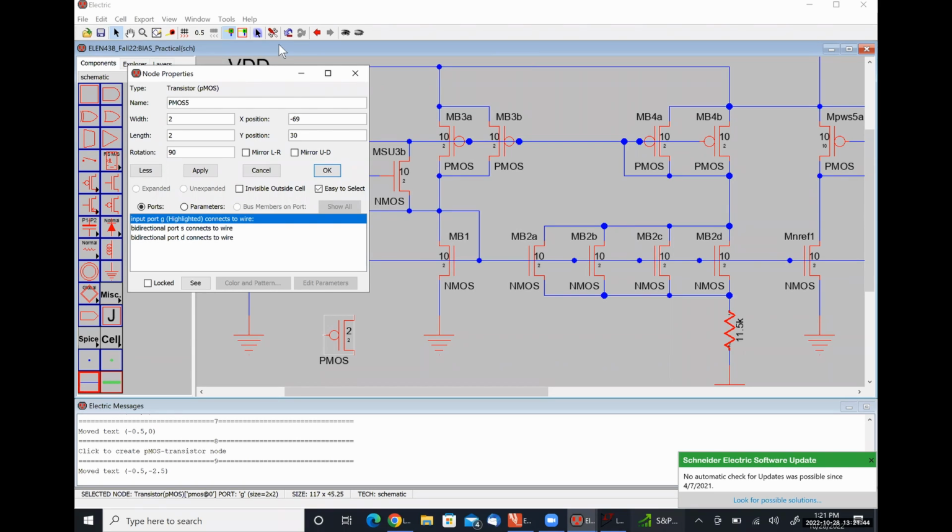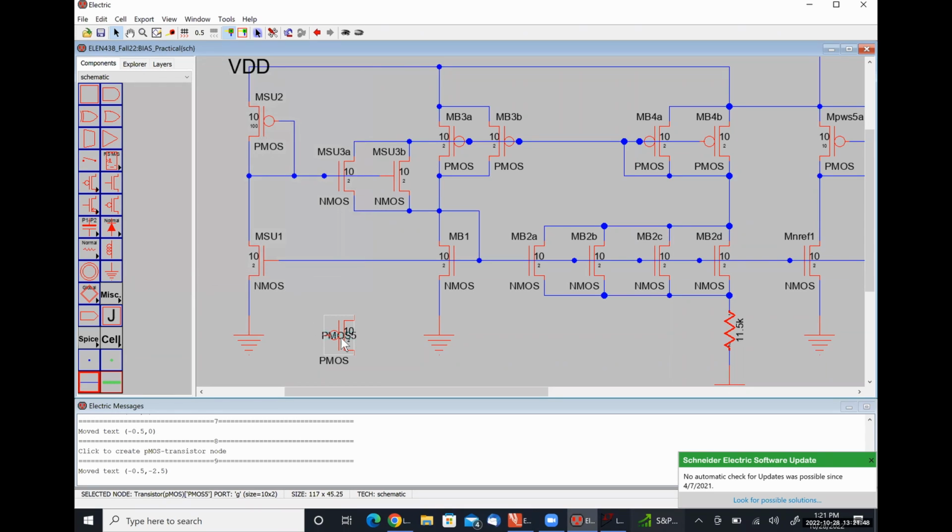And then with the transistor selected, I give it a name, PMOS 5, and give it the correct dimensions. And now that information is on there, and I move this up over here. And now I've told LTspice that when it sees this, it's a PMOS, and when I'm looking for it to find the current or something like that, it already has a specific label that's on the picture so that I don't have to go hunt through things. Did that clarify things, Gavin?